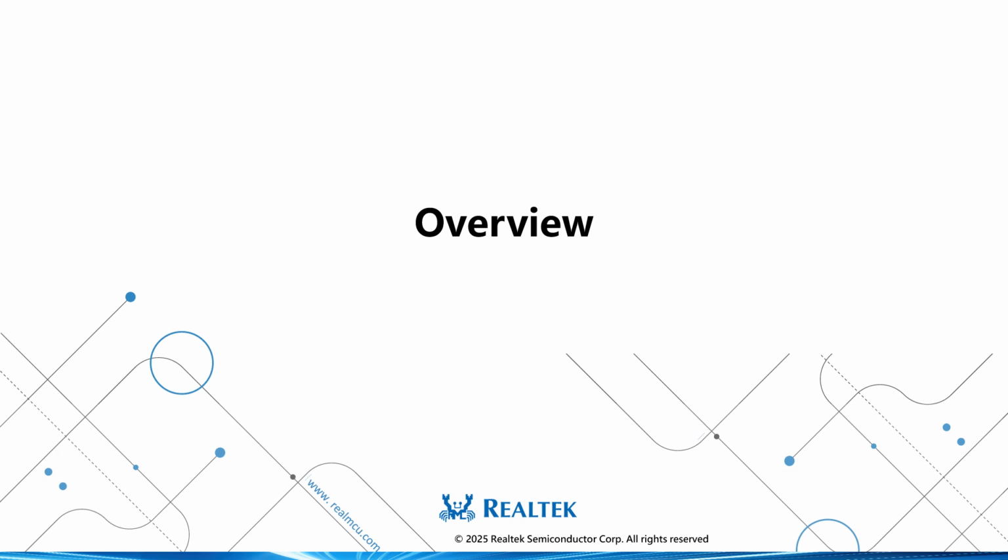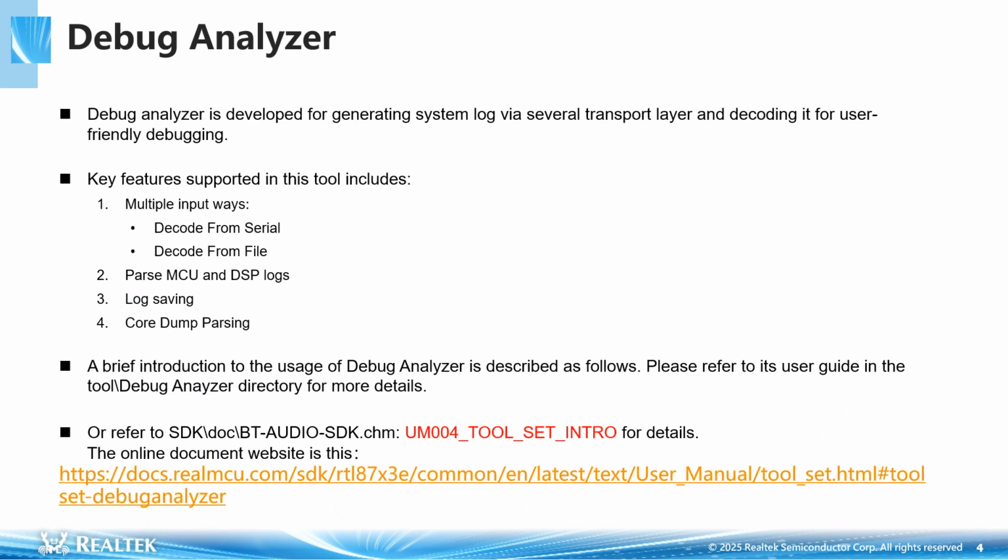First, let's have a brief introduction to Debug Analyzer. Debug Analyzer is a tool used for capturing and decoding logs of Realtek Bluetooth SoC chip. The key features supported by this tool include: 1. Multiple decoding methods, decode from serial and decode from file. 2. Parse MCU and DSP logs. 3. Log saving. 4. Core dump parsing.